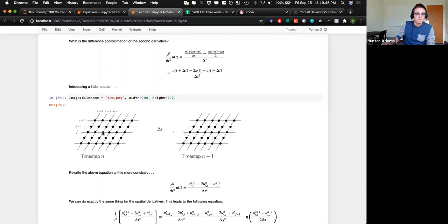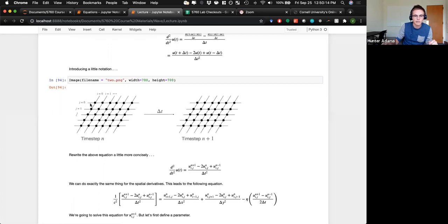And if we talk about that node at time step n, we use the variable n to indicate time step. The present time step we'll say is time step n, and the next time step, delta t later, will be time step n plus 1. So the full specification for a particular node will be node i, j, with the i's and j's subscripted. So we're talking about a specific node ij at a particular time step n. Like down here, we're looking at node ij at time step n plus 1.